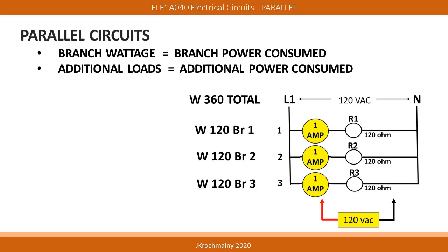In series electrical circuits, the more loads we place in series reduces the wattage of each load. In parallel electric circuits, each load gets its full share of voltage and as a result consumes higher wattages. This is why in parallel circuits, light bulbs are brighter. More wattage is being consumed. When wired in series, light bulbs are dimmer. Less wattage is consumed in these types of circuits.